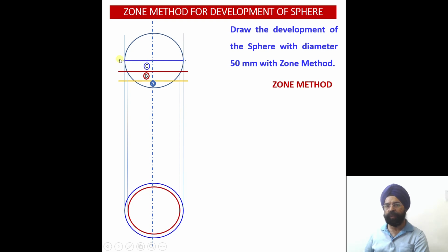Now you see, corresponding to all these, you see circles over there. This circle was there, this cutting plane was there at the axis point. So this circle will be represented by the outermost circle in the top view. Even if you cut this sphere into 50%, whatever diameter of the sphere will be there, it will look like a circle, because if you cut a sphere from any orientation in any position, the view you obtain for the cut surface will always be a circle. So if I have cut it from the center, this is my projection in the top view.